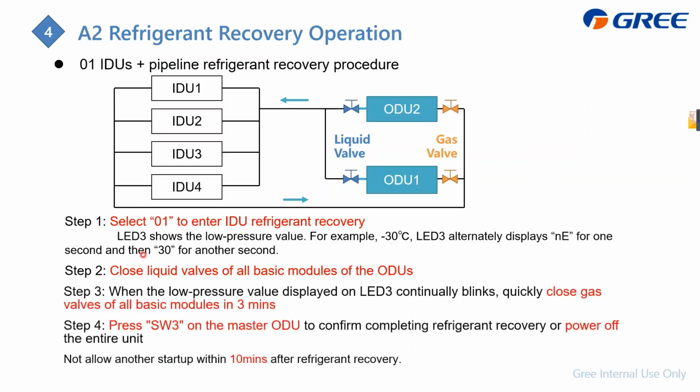And then the LED3 of the mainboard displays the low pressure value. And step 2, we should close the liquid valve. We should close this liquid valve first.